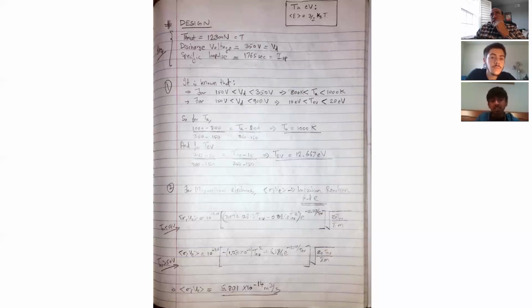So generally the electron temperature is in the range of about 10 to 50 electron volts. That's typically the range. Once we know this, this is actually a reverse calculation, to check whether the diameter, etc., of the thruster that we have modeled is according to the one given by the Aerojet data that I mentioned.